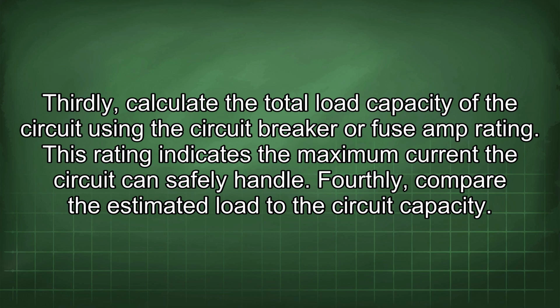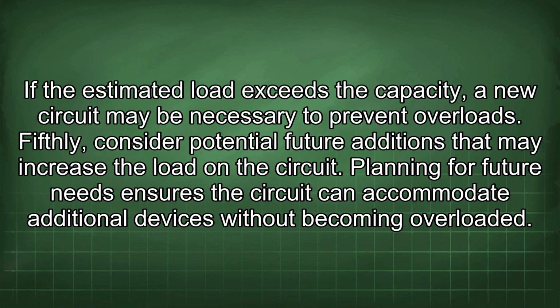Fourthly, compare the estimated load to the circuit capacity. If the estimated load exceeds the capacity, a new circuit may be necessary to prevent overloads. Fifthly, consider potential future additions that may increase the load on the circuit. Planning for future needs ensures the circuit can accommodate additional devices without becoming overloaded.